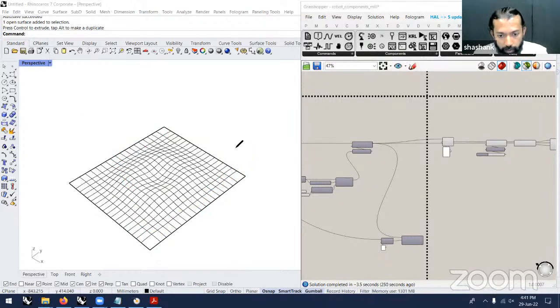So it would be nice if you had the robot go along this line, exit from it, and then go a little way to the left, go in the reverse direction, mill across this portion, and then again exit from it, and then try to create it. So every alternate set of points, every alternate point list, must be reversed so that you can optimize the travel time and you can optimize the milling time effectively.